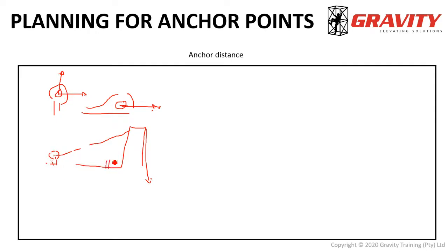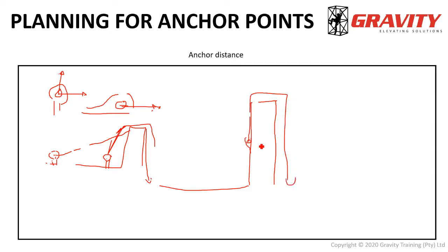If you put that eye nut closer to the parapet wall, again, you get closer to pulling it in the correct direction. Now, all of this, of course, can be avoided if you actually put your anchor points or your hangers, for example, in the parapet wall, as then you'll be in complete shear force, which is the safest, or if you put your eye nut, which we don't recommend, there. Okay, but again, bolting into parapet walls and those kind of things do come with its own limitations and its own restrictions, which you need to know. You have to be trained and competent to do that safely.